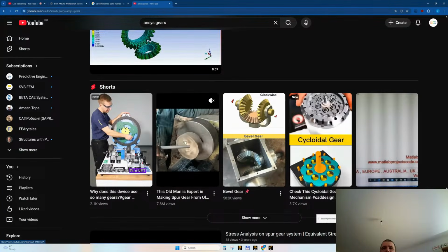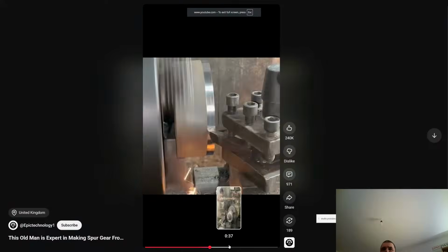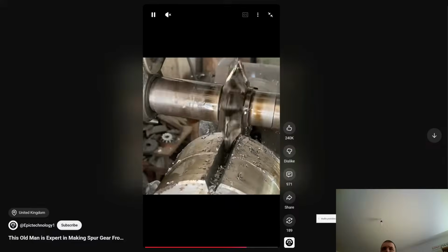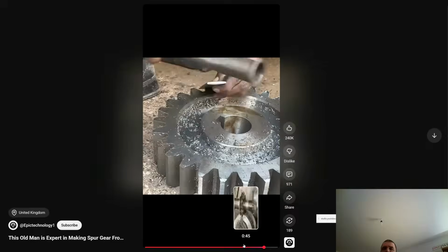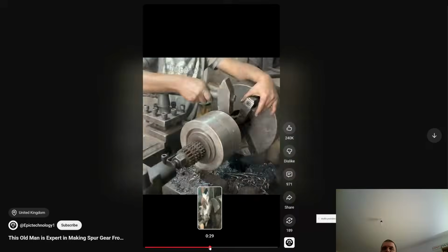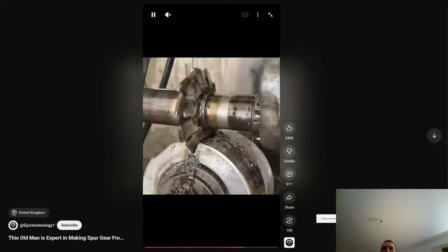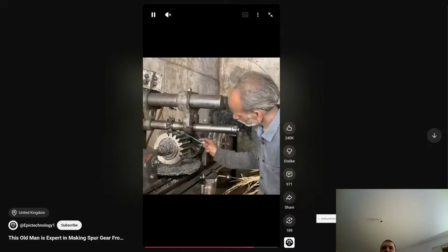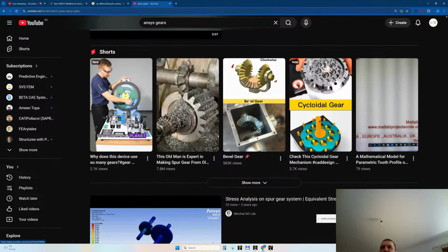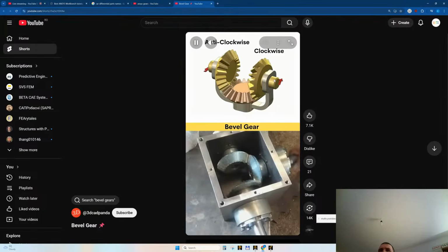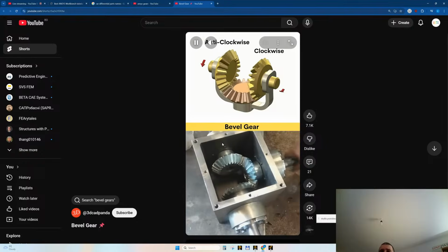And this is how a gear is machined. This is very nice. This is one of the methods to obtain teeth, with a profiled mill, a mill with an involute profile, machining the gear according to what we need. Yeah, very nice. As I said, these are in the housing, yes.